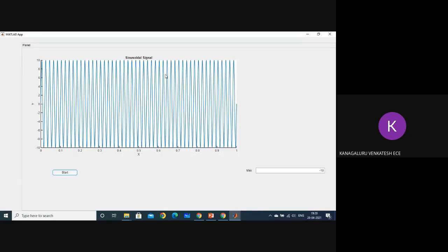So from the noise removed signal, you can apply some mathematical formulas. For suppose I have told here finding the maximum amplitude and minimum amplitude. So according to your own requirement, whatever feature, either it may be entropy or standard deviation or variance, maximum peak, minimum peak, all these features you can estimate, and based on that you can come to a conclusion. And if it is a biosignal, you can use it for diagnosis purposes.